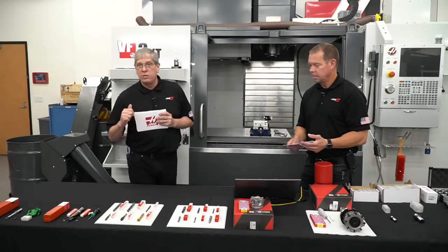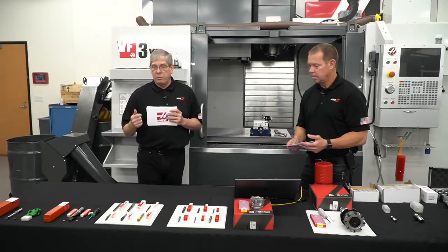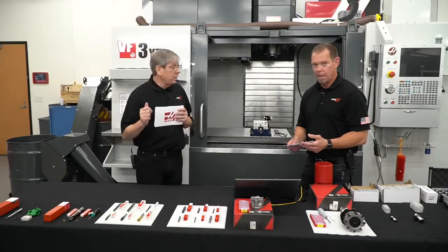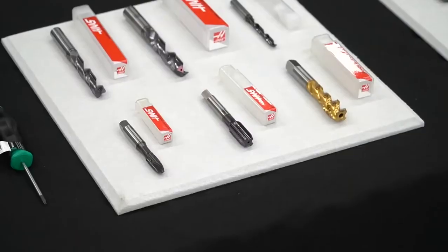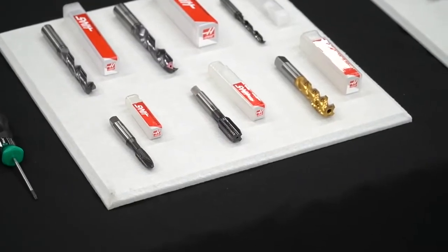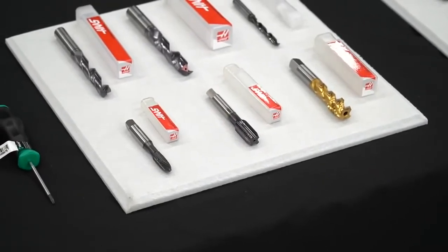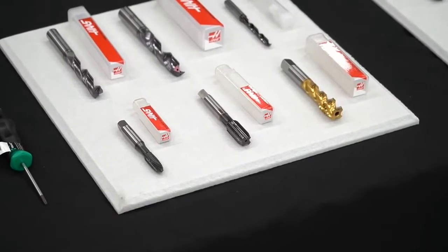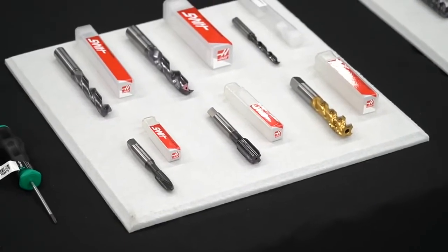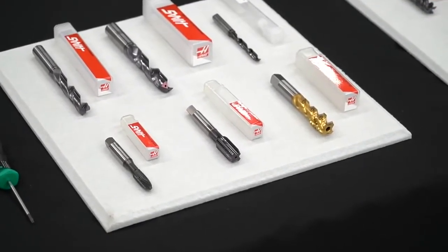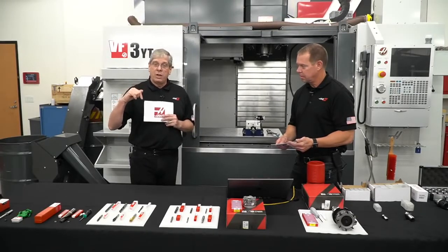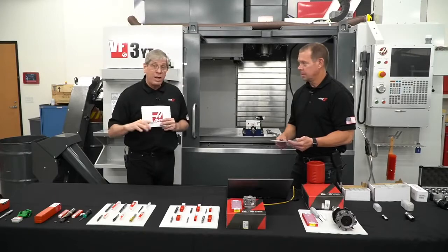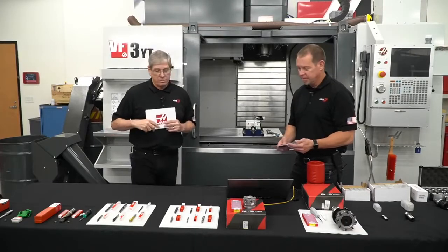There's a bright coating generally used on aluminum and non-ferrous materials. There's a hard slick coating. There's a titanium aluminum nitride, and titanium carbon nitride. So there's a variety of different geometries and coatings available on all of these. Check out the website, look up the best tap for your application. Also, we have to pay attention to whether you're tapping a through hole or a blind hole. All of that stuff really matters. So, okay, let's move on to end mills.